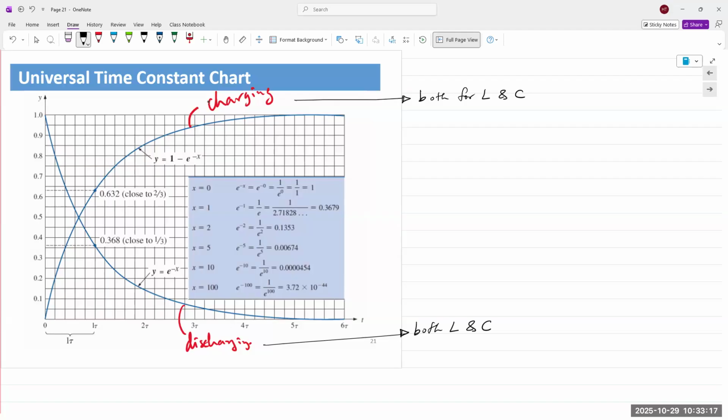Before capacitive touchscreens, we had resistive touchscreens. I don't know if you've ever used resistive touchscreens. I actually have devices with resistive touchscreens, but a finger tap would not work. You'd have to actually push down, force. And the reason is because it's measuring the change in the resistance by measuring the force that is applied to that screen. And so resistive touchscreens work better when you have sharp devices and you actually have a pinpoint that would be more accurate. And so the older kind of touchscreens used to have a stylus to use them.